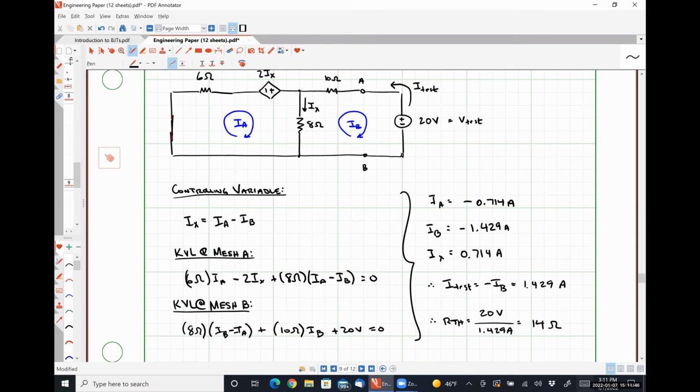So let's take a moment now to effectively rework this portion using a test current source so that I can illustrate how you go about using that and prove that it's going to give us the same thing. Colby, what's up? So we could have picked any number other than 20 and it would still give us the same. Exactly right. And it's because our circuit is linear, we've proven that the excitation scales, right? The homogeneity factor.